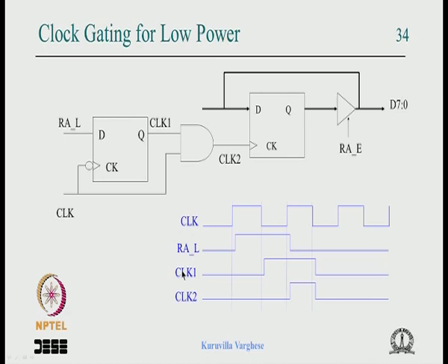So today we have completed the Mealy and Moore output, and we have seen where Mealy can be safely used. We have looked at the clock gating solution and the recirculating buffer: what the timing issue with clock gating is, and how it is avoided in the recirculating buffer. But the issue is power dissipation, and we have seen a clock gating scheme for low power. We have also seen the extension of the recirculating buffer for multiple control signals where there is priority, how to design it, how to code it, and all that.